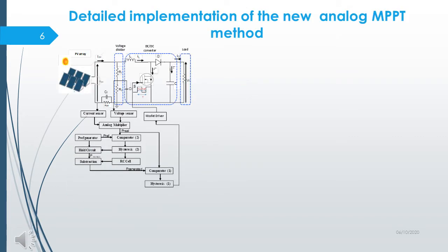A novel analog MPPT technique suitable for PV system applications is presented and validated by simulations using the circuit-oriented simulator approach such as ISIS. The proposed analog technique is based on the generation of a reference power signal, PREF, to be followed by the PV panel's real power, PREAL, since this PREAL is lower than the maximum power generated by the PV panels. This figure shows the simulated different waveforms corresponding to the above-mentioned power at different irradiation levels.